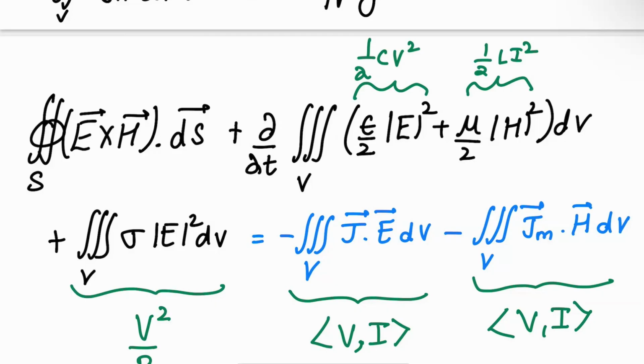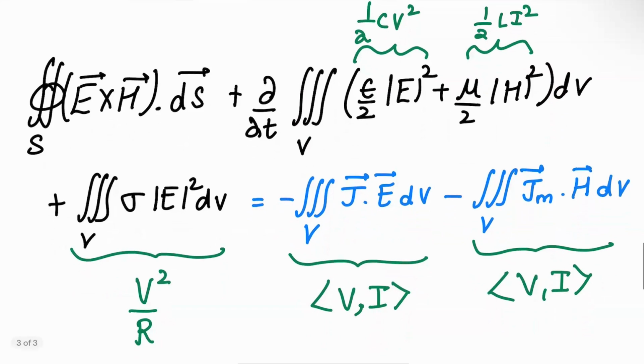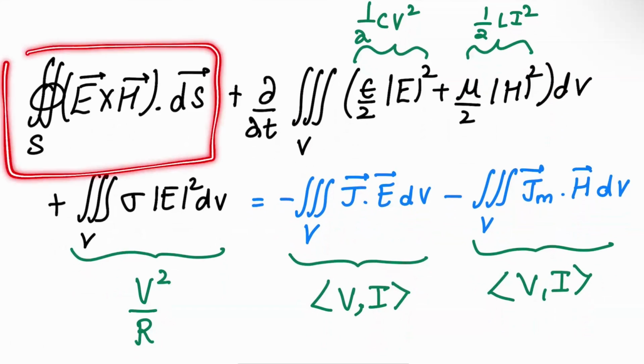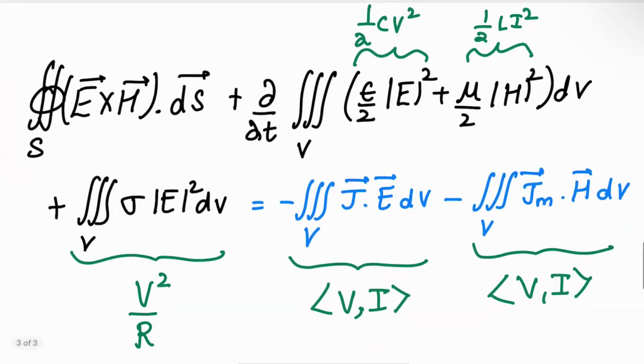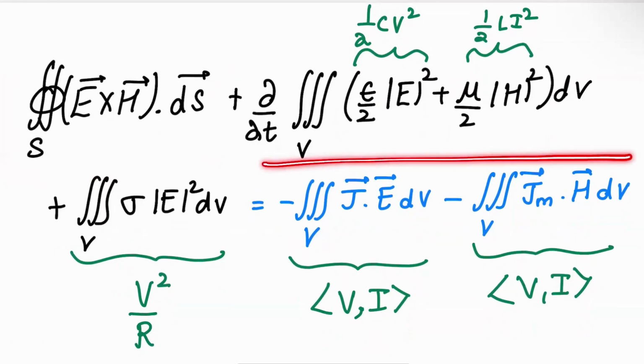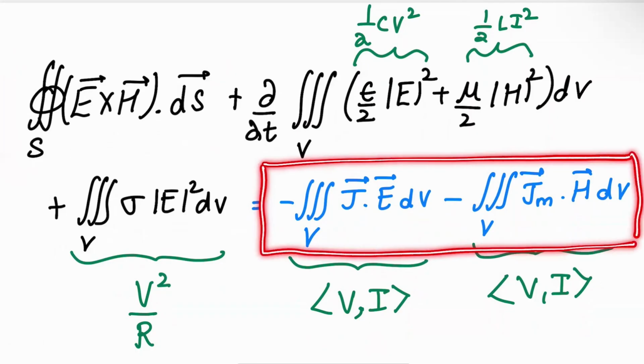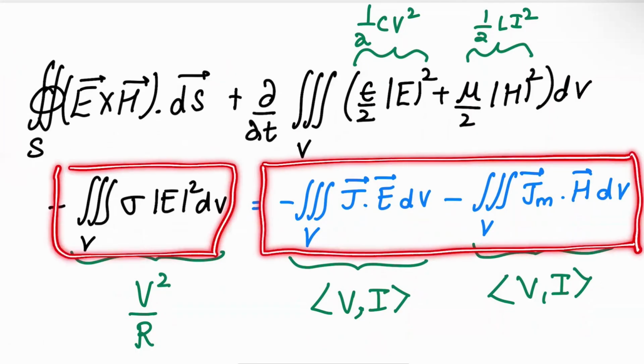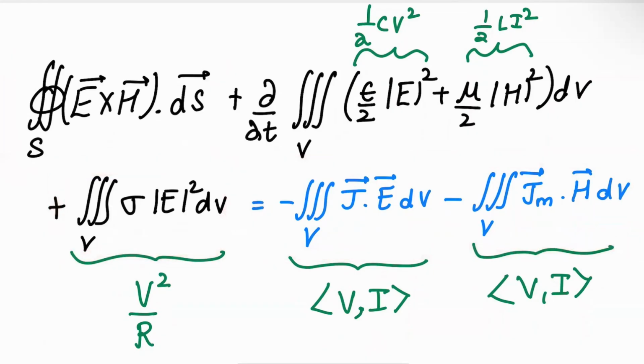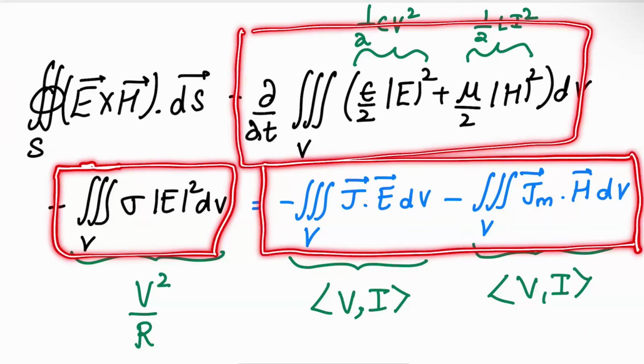So this term is the amount of energy stored in the electric and magnetic fields in that medium. And the derivative of that is the amount of power in that medium, right? And power is the time derivative of the energy. So this is the last remaining term which we will interpret. So what is this saying? This is basically saying that you have some power supplied on the right. Some of that power is going to the loss in the medium, so it's converted to heat. Some of that power is being used to increase the energy in the medium, right? And then this is the last term.